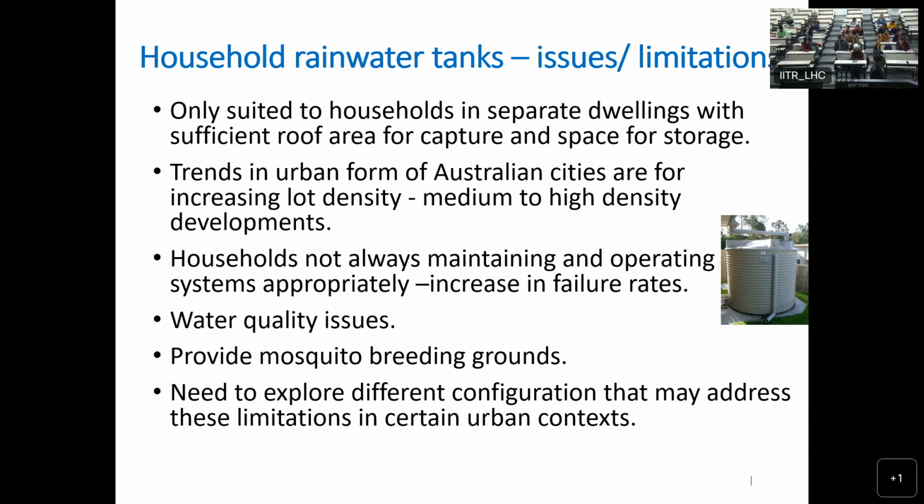If the pumping is only for, say, 12 hours, your mass curve will change, because the input is only for limited hours. Then the deficit and the maximum value will be quite different, so the capacity will be significantly different.